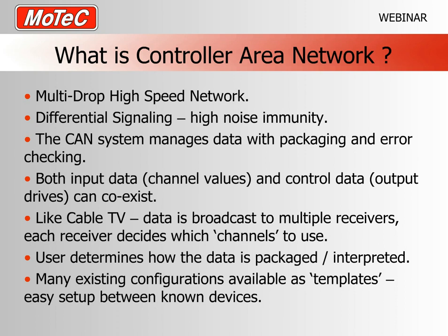For example, our ECUs and our dash loggers can communicate with each other very simply using the predefined templates that come with the system. So you don't need extensive knowledge on these devices to make the CAN communication system work. If you use the supplied templates, you can get things plug and play in a very short amount of time.